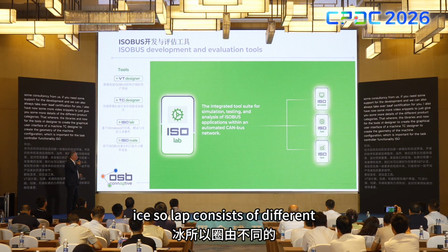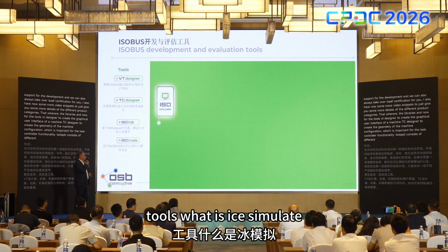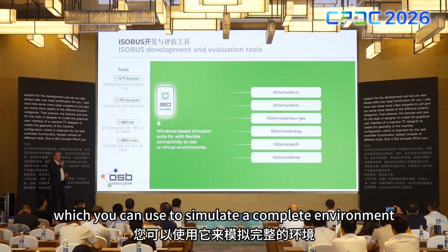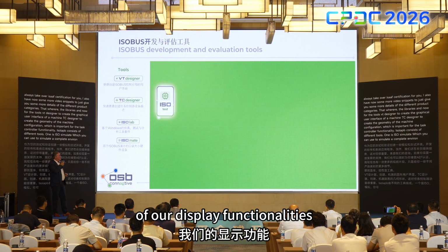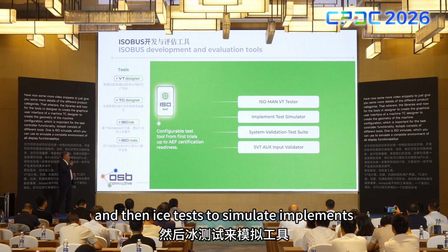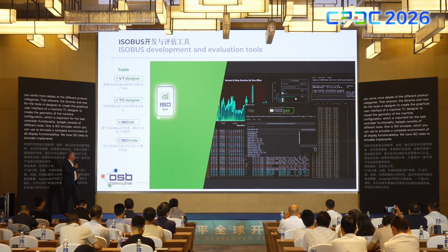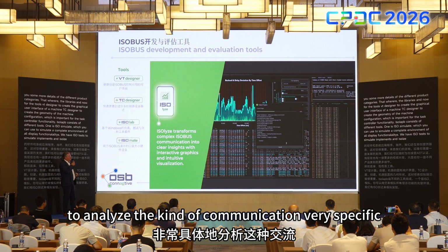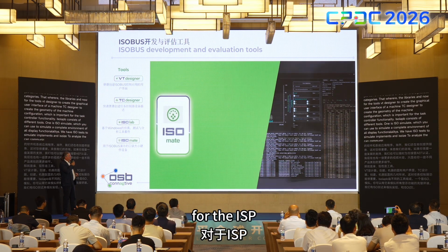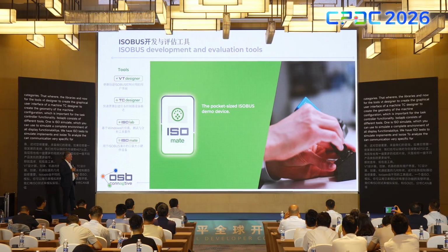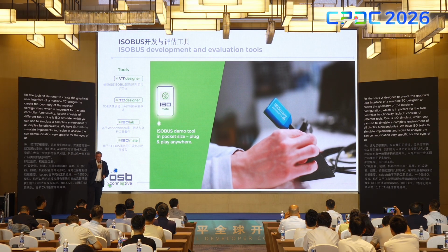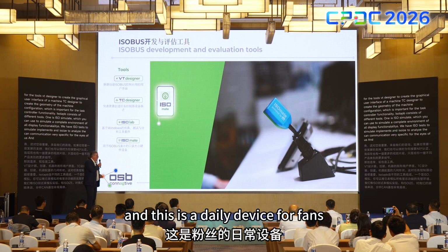It consists of different tools. One is ISO Simulate, which you can use to simulate a complete environment of all display functionalities. And then we have ISO Test to simulate implements. And ISOLize to analyze the CAN communication, very specific for the ISOBUS. And this is a demo device for fairs.